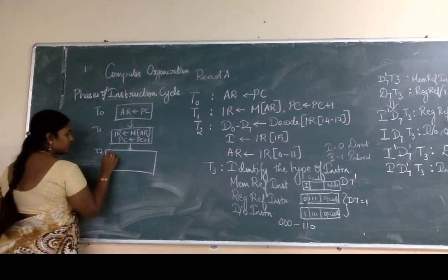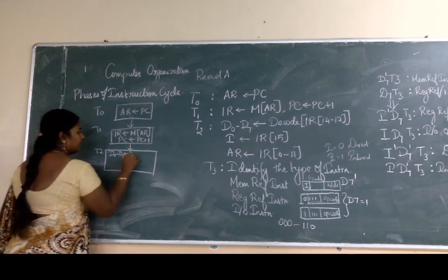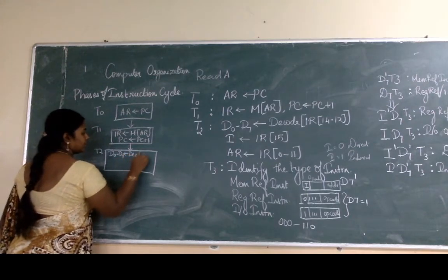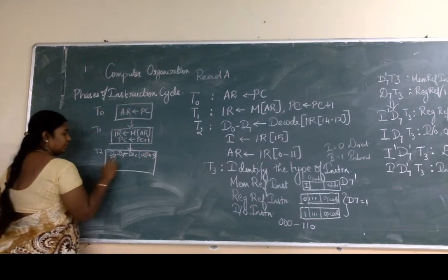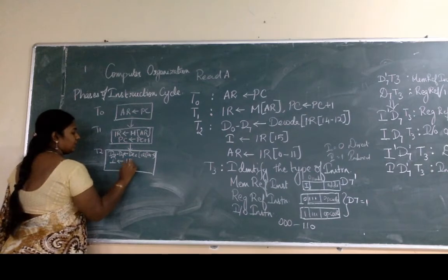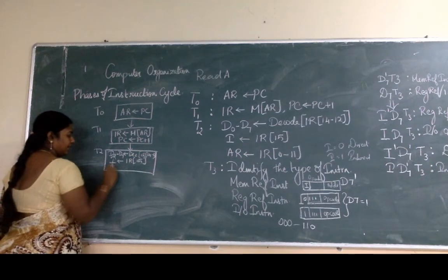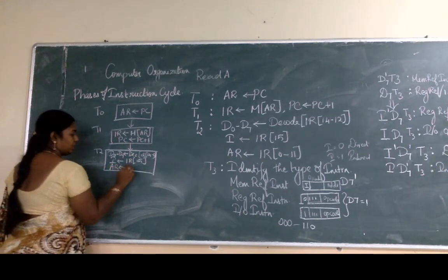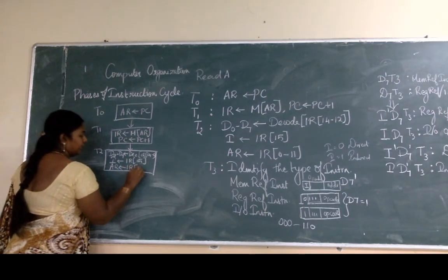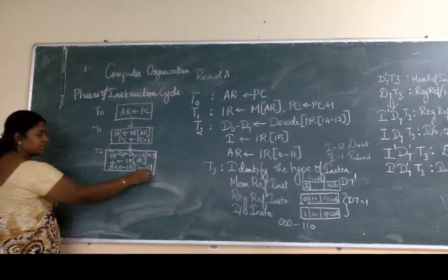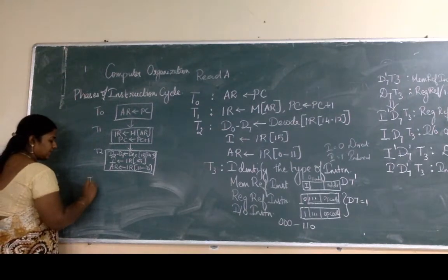The first one is loading of D0 to D7 from the decode of the instruction register bits 14 to 12, flip-flop I loaded with bit 15 of the instruction register, and the address register being loaded with bits 0 to 11 of the instruction register. So this is going to be time cycle T2 and then time cycle T3.